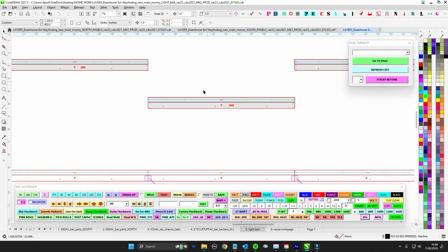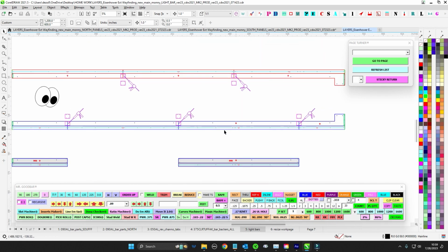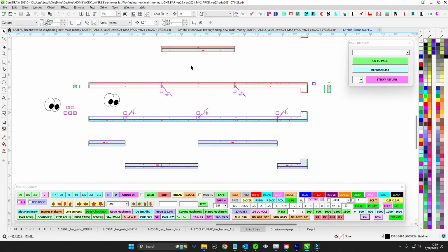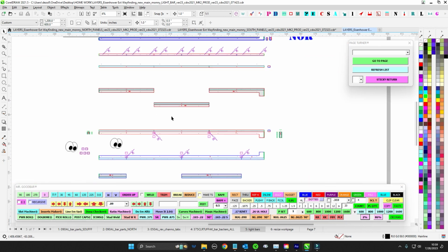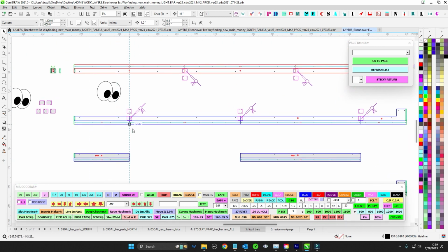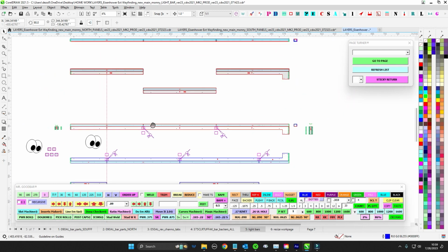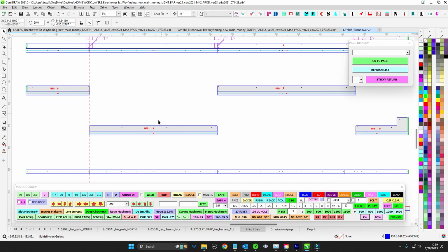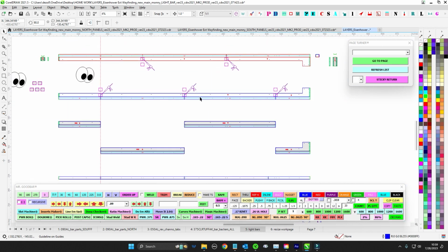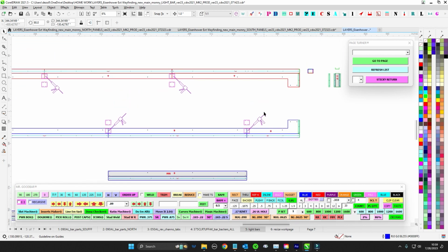So you're going to have the top side, the ones in red here, and then the bottom side is here. And then the faces, when they come together, will make the lamination. So you can see where the staggered seams of the bottom will meet in the middle of the red, and the seam of this red will meet in the middle here, et cetera. When you're done, you'll laminate together the faces and you'll have your contiguous top and bottom.